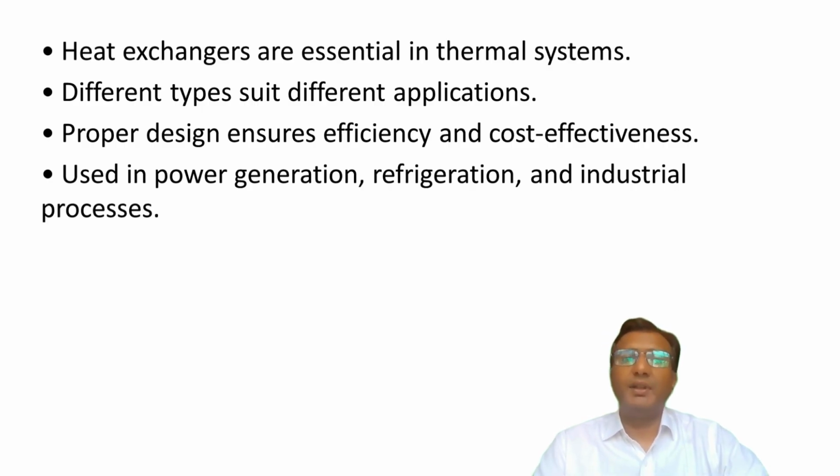To summarize, heat exchangers are essential devices for transferring heat between fluids, playing a critical role in thermal systems across industries. They operate via conduction, convection, and sometimes radiation, with flow arrangements like parallel, counterflow, and crossflow affecting efficiency. Types such as shell and tube, plate, and fin tube exchangers suit diverse applications, from power plants to food processing.